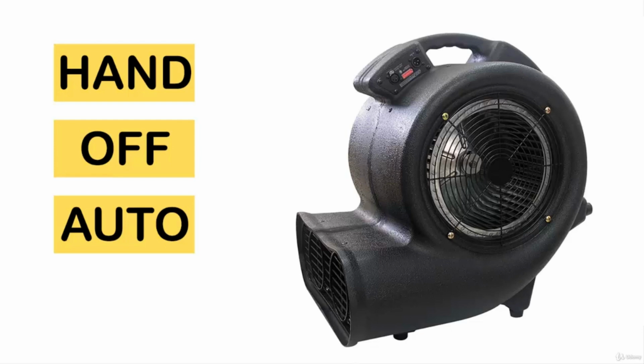So with that in mind, we're going to plan for 3 input buttons, one for hand, one for off, and one for auto, and 1 digital output, which is going to our blower, and we're going to write the control logic that allows those 3 buttons to set the status of this blower and ultimately send the signal out to cause the blower to run.